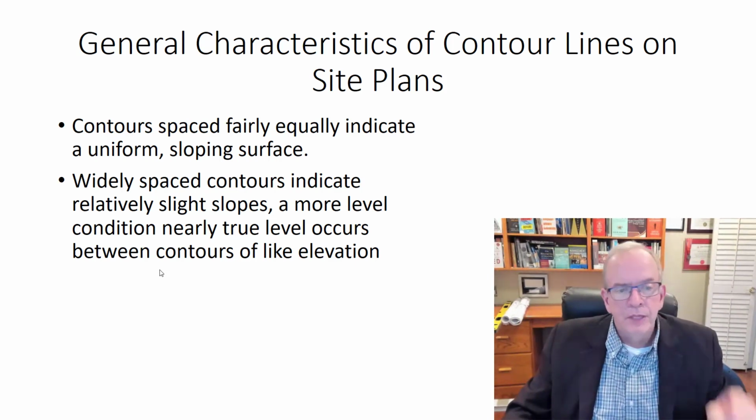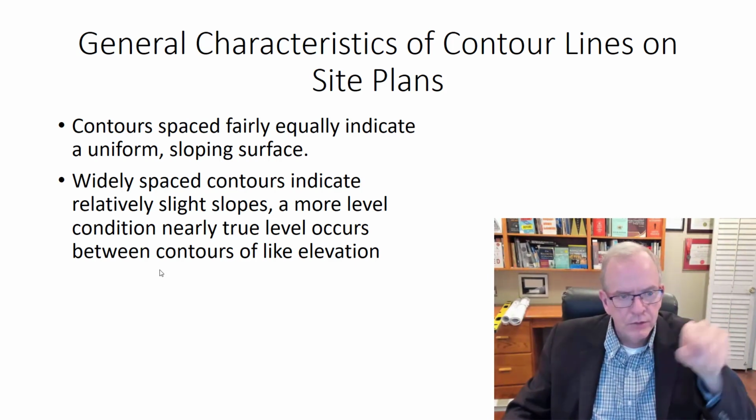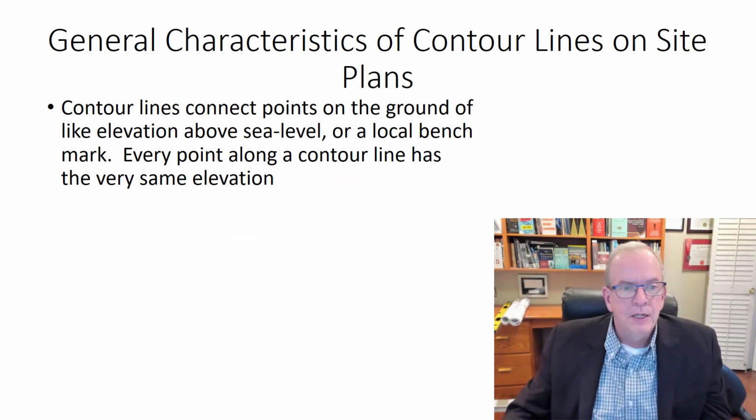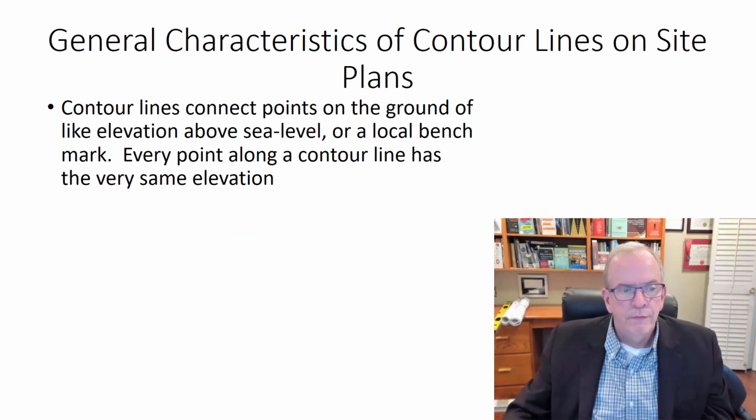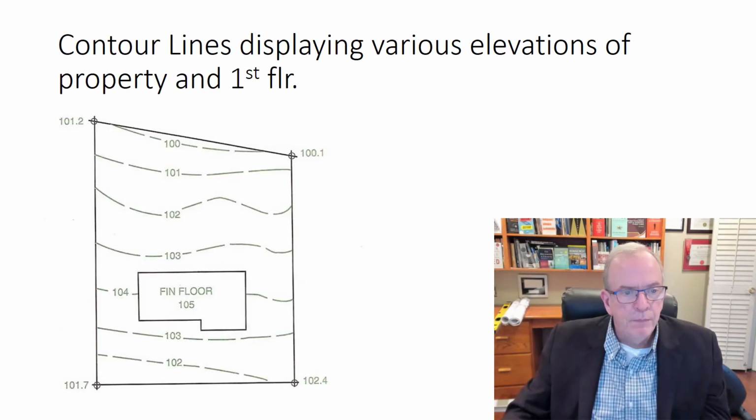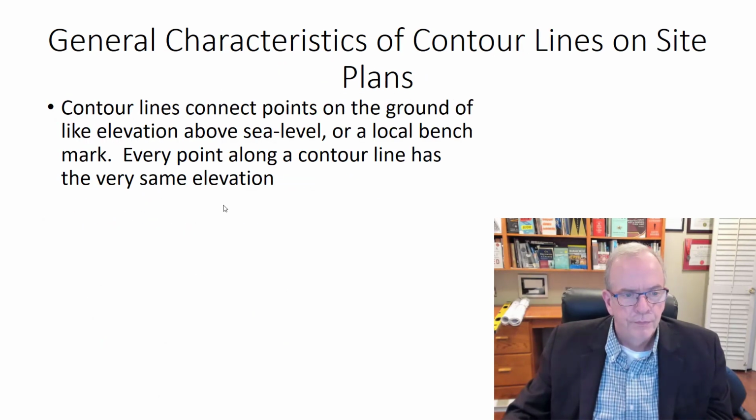In this example today, we'll look at where the contour lines are pretty close, and that just means it's steep in that particular area, and that when they connect around, they basically form that sort of hill or pond that I was mentioning. But you've got to remember that every point along this line is telling you that it's at that elevation. So if it squiggles off a little bit, that means that it changes in elevation at a certain point. And I think this one is actually the existing grade, because it's kind of off in a few spots. More likely when this would have been finished graded, it would be probably more even of a slope.